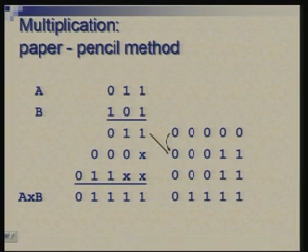So, basically you are carrying out addition of initial 0 value and this partial product to get this, then next one is added, and then the next one is added. So, as you can see, the whole thing breaks up into multiplication by 0 and 1, shifting by successively 1, 2, 3, 4, so many positions, and adding all these up.